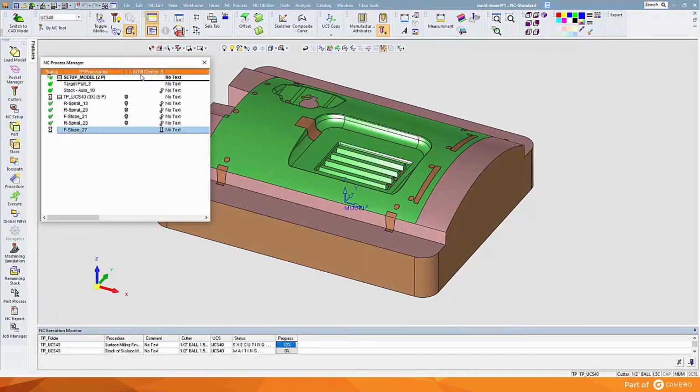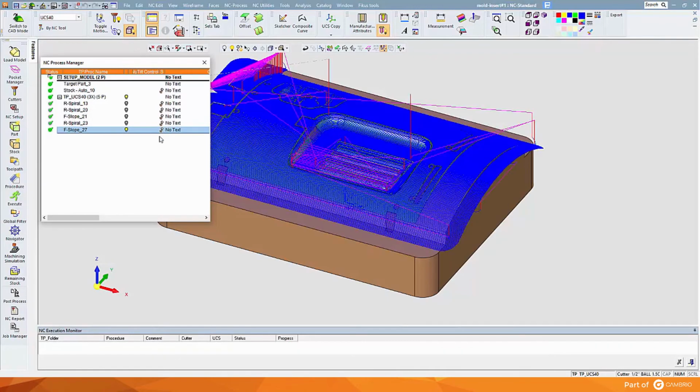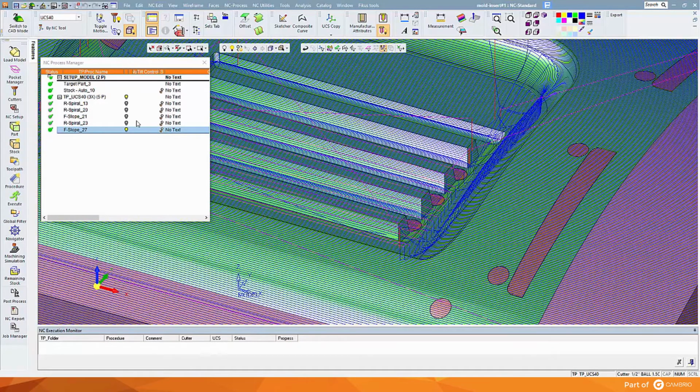The results are tool motions that lift away from the louvers while finishing all of the details selected as group 1 to 0. That brings me to the last 2 items I wanted to discuss today. The first is multi-cutters. It's an option within finish milling and remachine procedures.